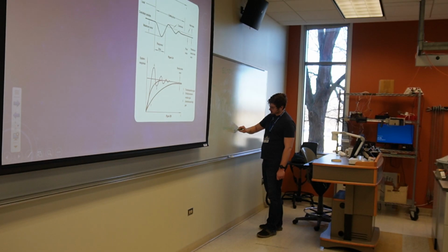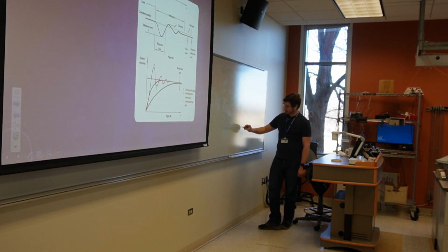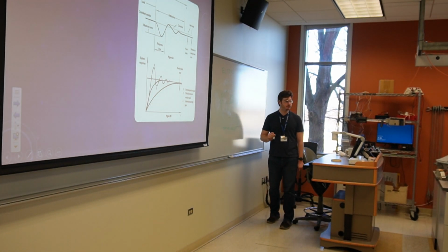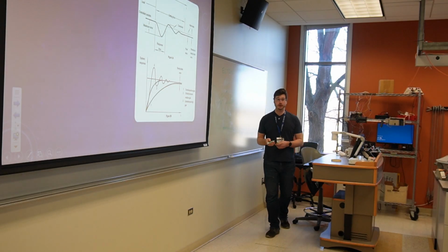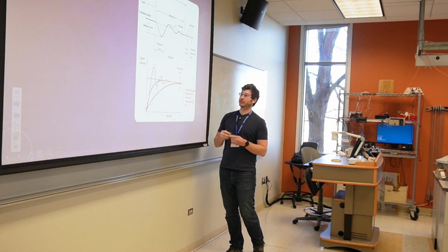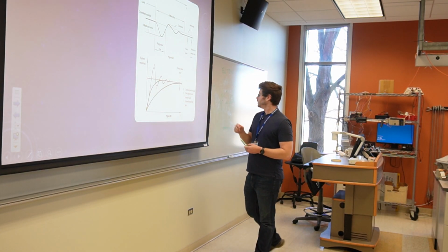If we tried to correct, maybe our smallest step brought us a little bit over the line, and our smallest correction would only bring us a little bit above or a little bit below that line. That would be our steady state output, or our residual steady state error, rather.